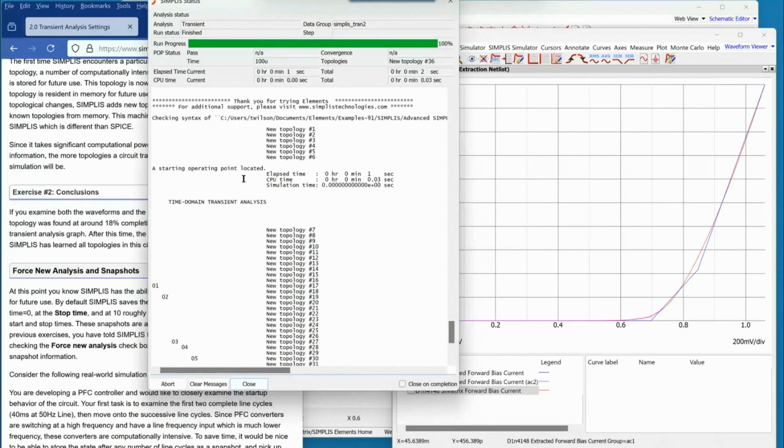Yeah, I think what you would do in that case is take your modified SPICE model and give it a unique name. Don't call it a 2N2222, or a 1N, whatever. Call it, dash Chris. So give it a unique name and then put that into your SPICE library. Yeah, I can do that. That works quite nicely.